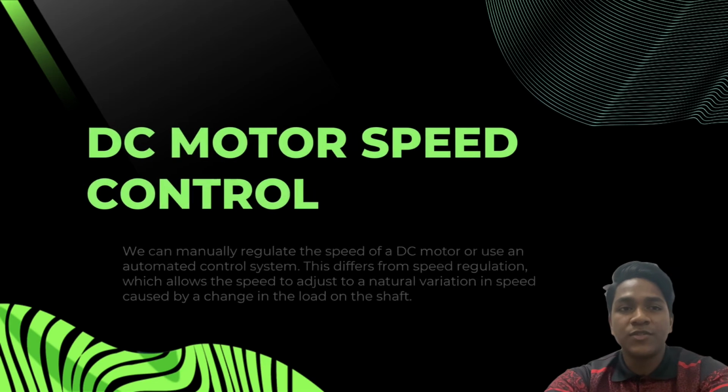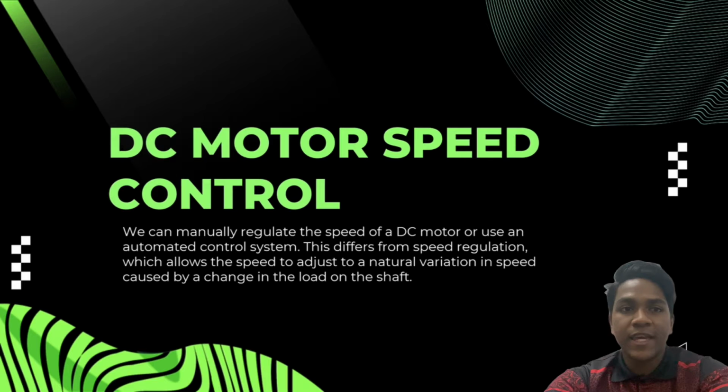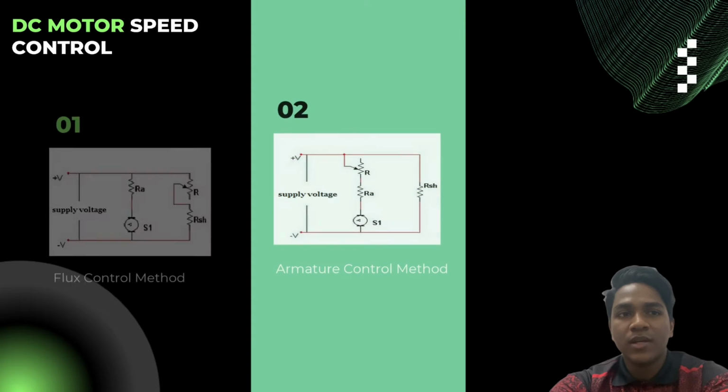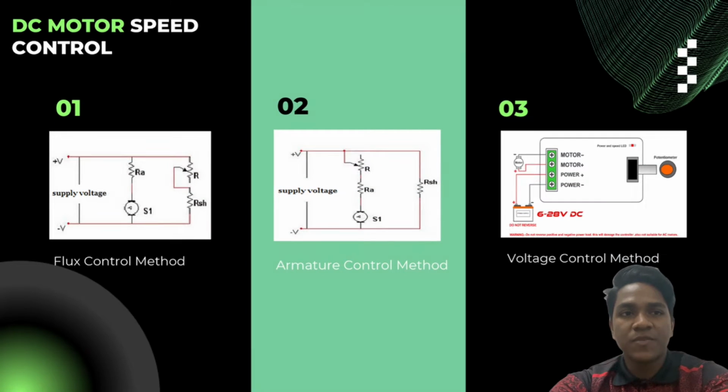We will move on to DC motor speed control. We can manually regulate the speed of a DC motor or use an automated control system. This differs from speed regulation, which allows the speed to adjust to natural variations in speed caused by a change in the load on the shaft. There are three DC motor speed control methods. Number 1 is the flux control method. Number 2 is the armature control method. Number 3 is the voltage control method.